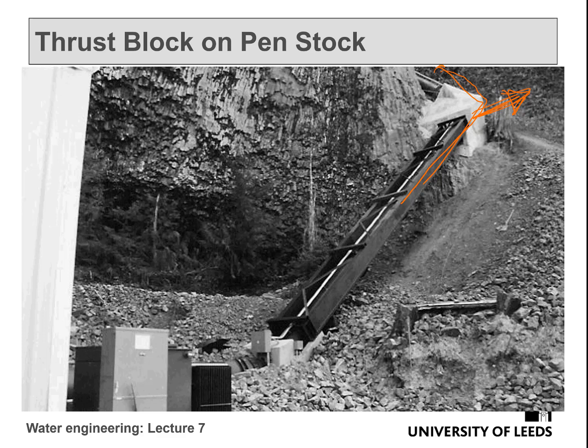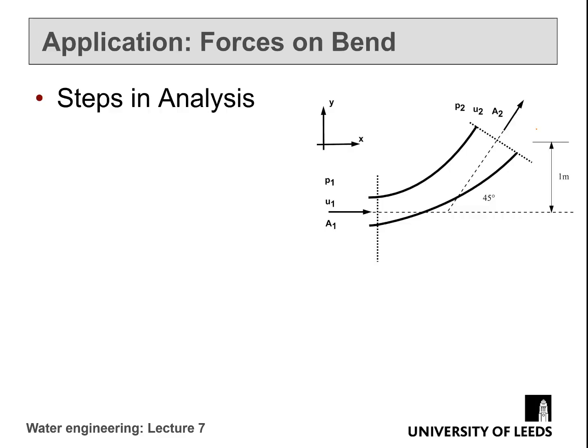That's tied into the stone of this mountainside, and it's this force Fr that we're trying to calculate. Well, it's actually Fr, remember, is the force on the fluid. We're trying to calculate R acting out on the bend if we want to design that thrust block. Right, let's get started. First of all, we'll look at the problem.